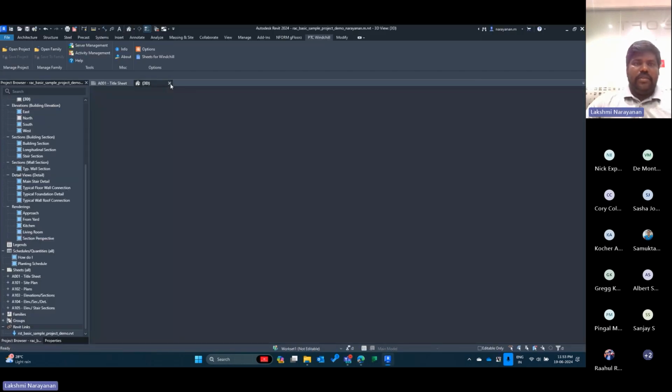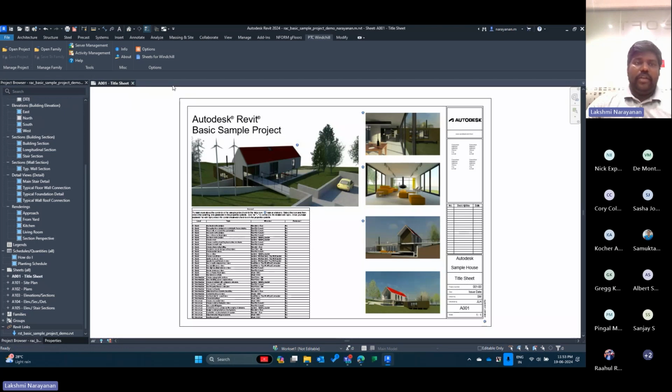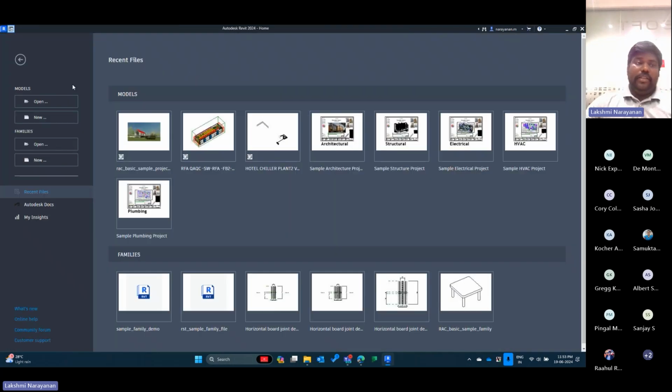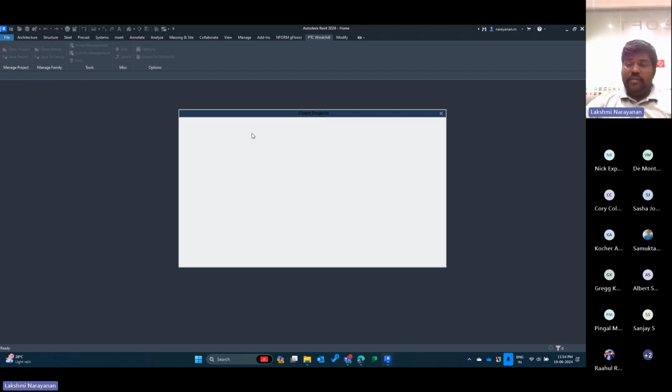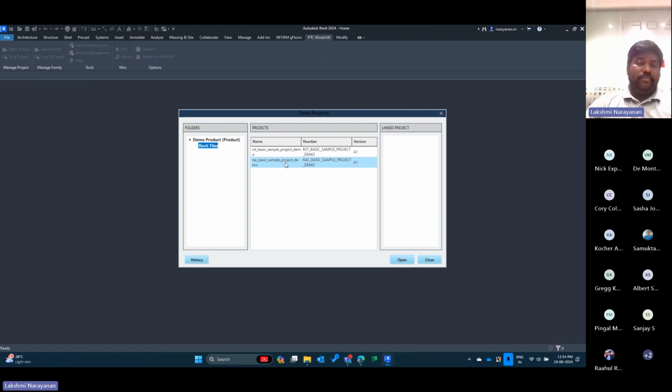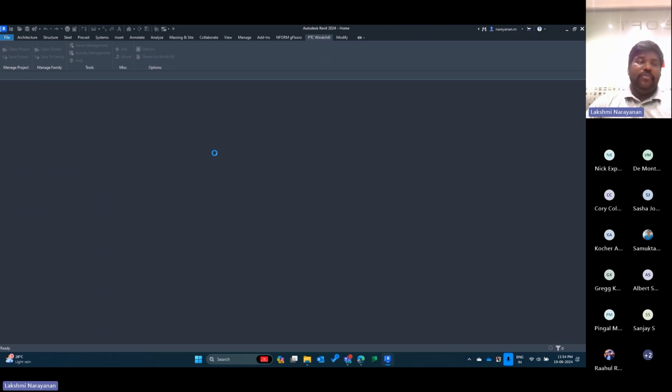Once the design is saved, the user needs to close and reopen the design from Windchill to work directly with the design copy from Windchill. Now all other users, wherever they reside in the globe, can open the design directly from Windchill. The user need not have access to any file server or common network path where the Revit file resides. If they have access to Windchill, they can directly go ahead and open the design from Windchill.